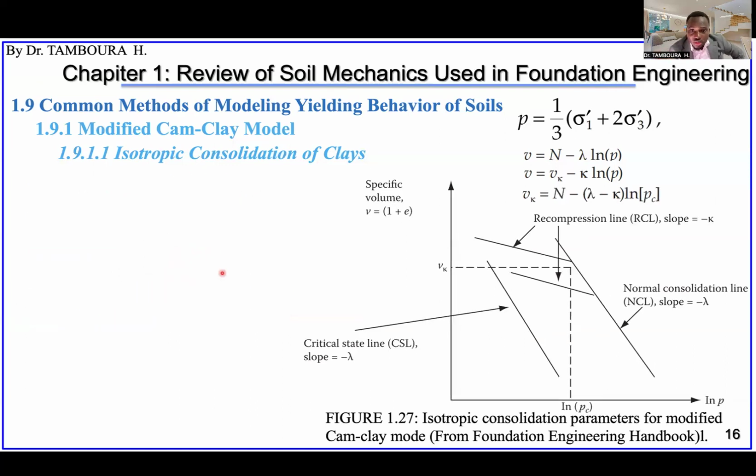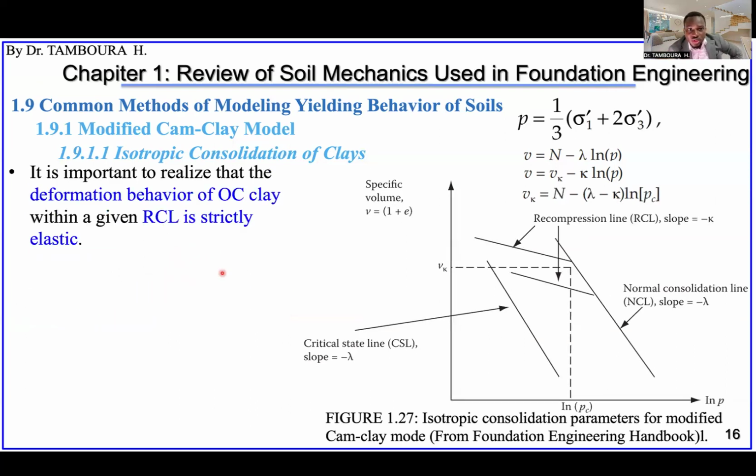That's all. It is very important to realize that the deformation behavior of over consolidated clay with a given RCL, this line, is strictly elastic. This line is elastic because the soil has experienced the stress at this level before.